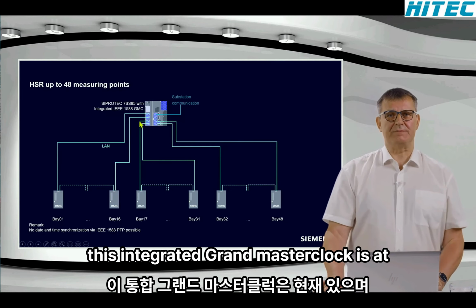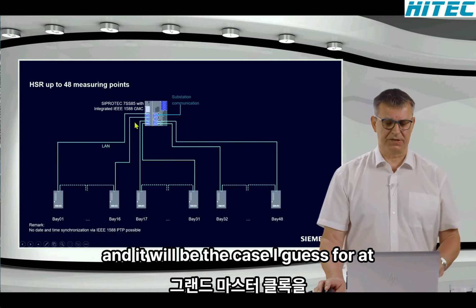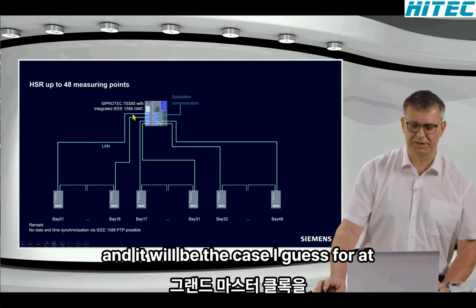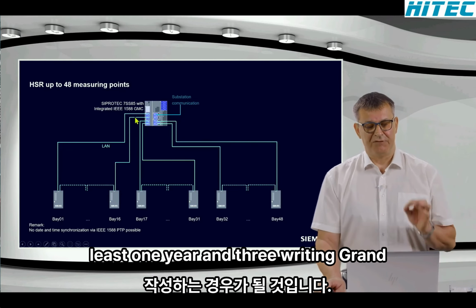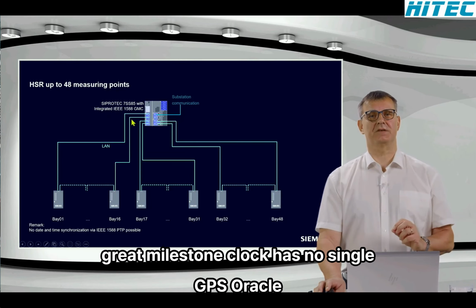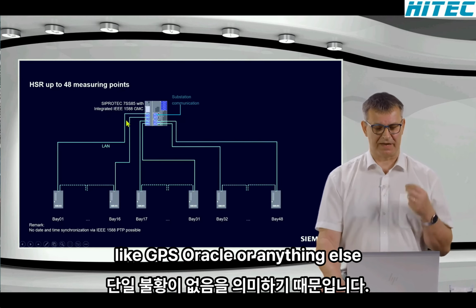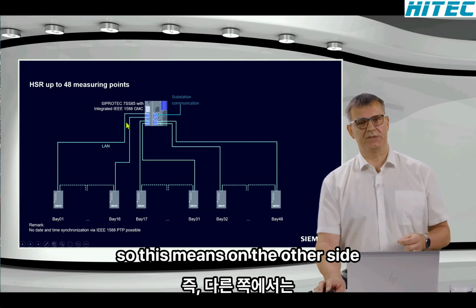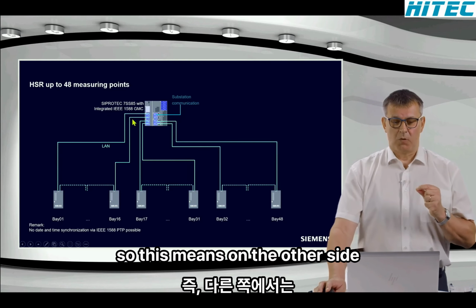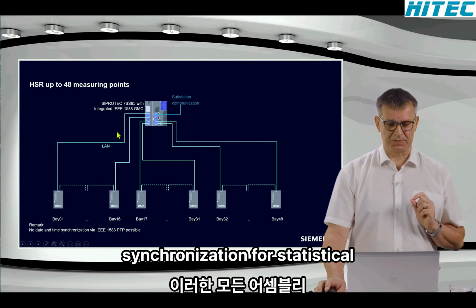This integrated grand master clock is at the moment, and it will be the case, I guess, for at least 1 year, a free running grand master clock. And this means this grand master clock has no synchronization with a local time network like GPS, IRIG-B, or anything else. This means on the other side, we can do only the sample synchronization for the distributed busbar protection.